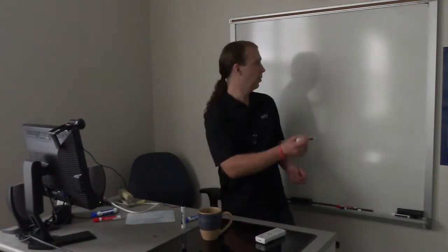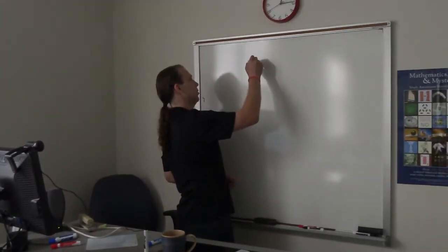And we assume that the clock signal that drives that finite state machine is very fast. So in other words, any change, any input a user makes is going to be picked up not immediately, but in a very short amount of time when a new rising edge of the clock signal comes in.